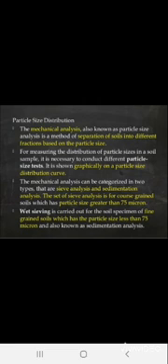So the third point is that the mechanical analysis can be categorized into two types. The very first one is your sieve analysis, and the second is your sedimentation analysis. There is a word called sedimentation. What does it mean? Whenever we put any type of waste or soil in standing water for a specific time period, for 24 hours or maybe more, the particles in the water settle down rather than staying as diluted particles. That process is called sedimentation, right? So there are mainly two processes: the very first one is your sieve analysis and the second is your sedimentation.